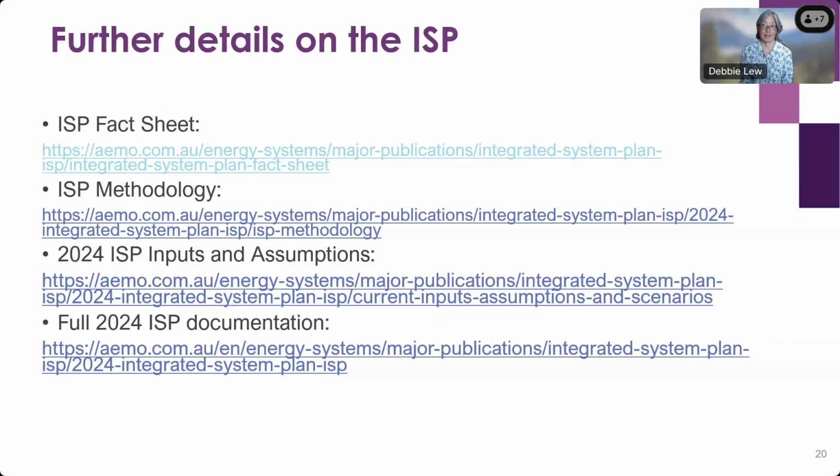That's why we try methods like optimal power flows and fictitious SVCs in part of the network to try to represent the voltage stability aspects going forward. But it does slow us down from being able to just automate getting hundreds of load flows out for all these future systems.